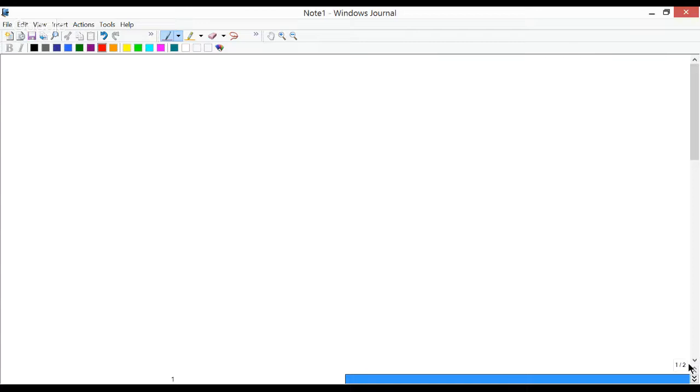The second question: heat generation in resistance spot welding is mainly dictated by what? I explained elaborately during this course that it is the contact resistance of the interface between the sheets to be welded. That is the rate controlling resistance in generating heat in resistance spot welding. Question 3 in assignment 2: when electrode force in resistance spot welding increases, what happens? Contact resistance decreases because you are giving more force. Good.